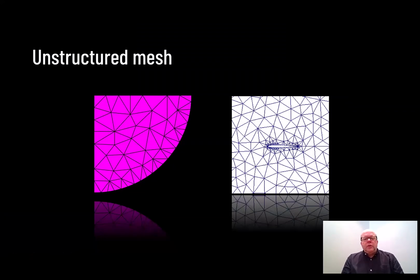So an example of an unstructured mesh looks like this. You can see that you have triangles, and you have also points added inside the geometry and on the boundaries that have been added to the geometry to create the elements. On the right example here, you have an aircraft wing, and then you have the elements generated around that. So basically you have a boundary, and then you fill that area with elements, and that is the purpose of the algorithm.